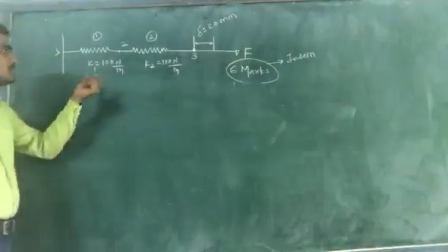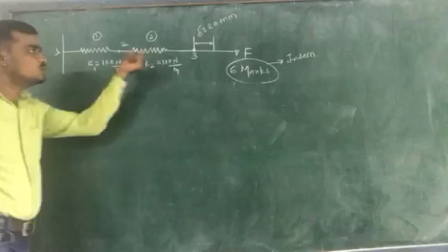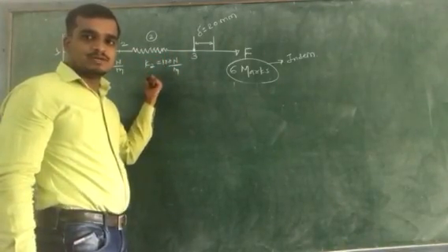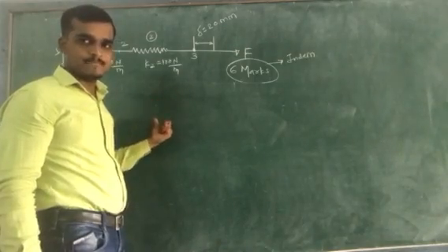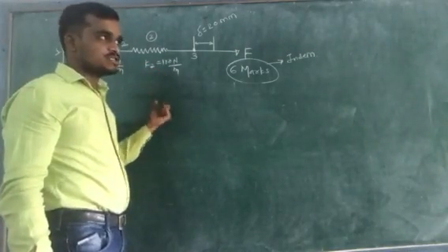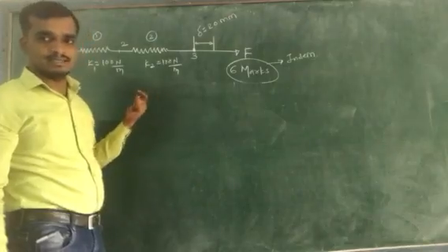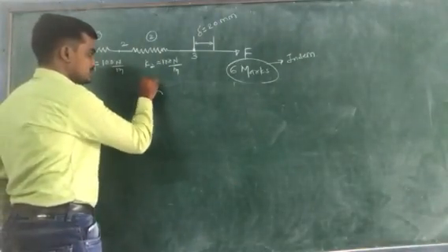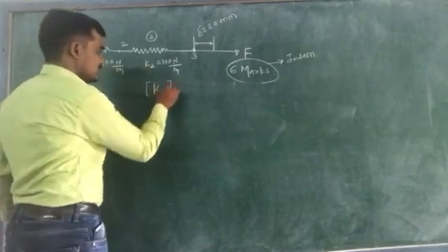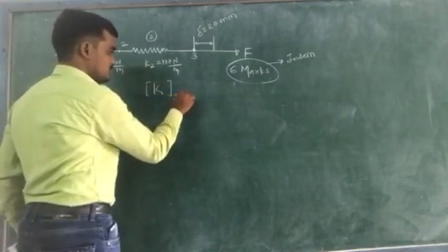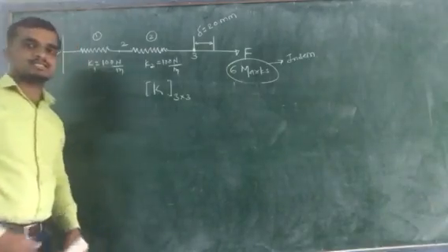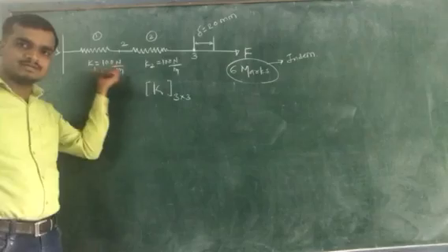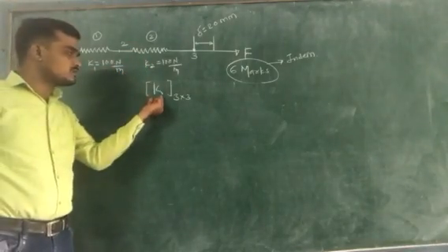As there are 3 nodes, 1, 2 and 3, the order of the global stiffness matrix will be 3 by 3. So first we construct the elemental stiffness matrices for these two elements, then by using them we construct our global stiffness matrix.